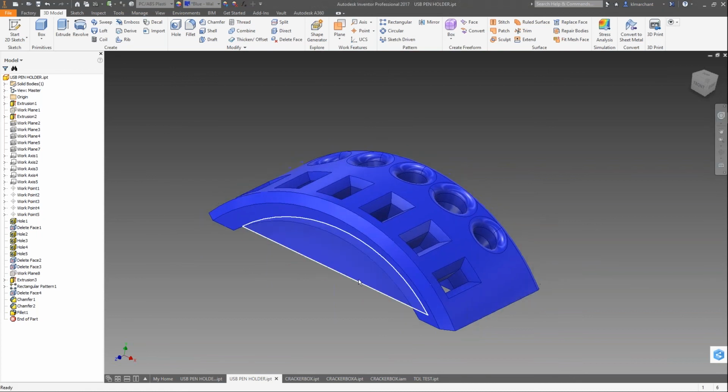So with a little bit of design thought between temperature control, overall material use, and layer detail, those are all very important, especially for FDM and FFF technology. Our CJPs have much tighter control over the layers. The huge advantage there is the reusability of the support, because it's the same as the print material, just unbound. And we can throw graphics on those as well, give it color if we have a color-enabled printer. So that's a huge advantage of CJP technology.